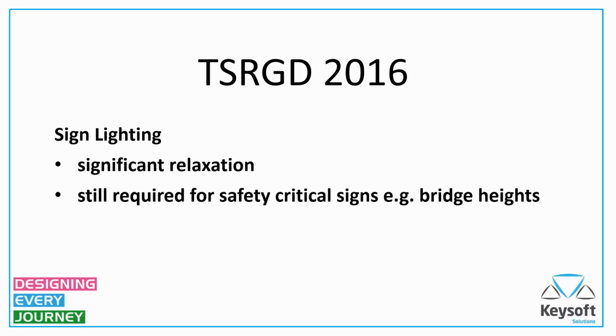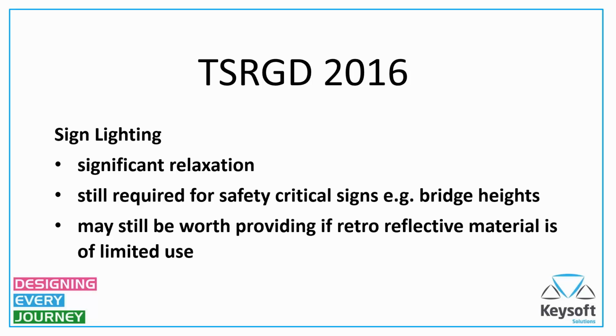So do bear that in mind, particularly the warning on low bridge heights. But do be aware that just because the regulations relax the requirements for things like sign lighting, it may still be worth providing, particularly if the modern retroreflective materials are not suitable for a particular site.